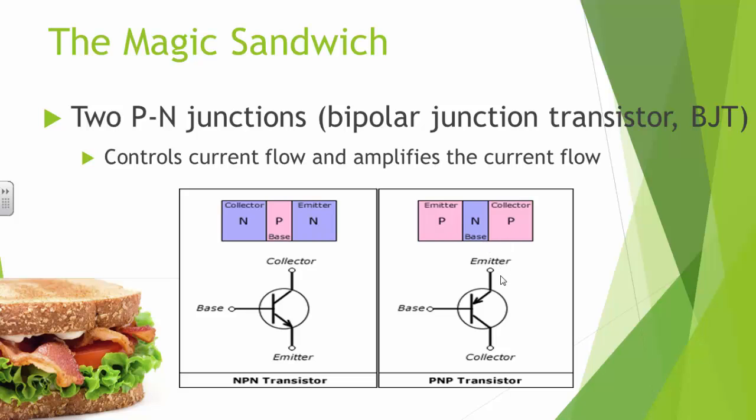In this case, if you think this through, and if you draw the diagrams like you saw in the previous slide, you'll see that the potential applied in one direction will result temporarily in a little bit of flow that almost immediately stops because it reaches the next junction. But the same thing happens for the other one. Essentially, electricity can't flow in either direction. So by putting two diodes against each other in that way, we've made it so that electricity can't flow in either direction. Not very interesting.